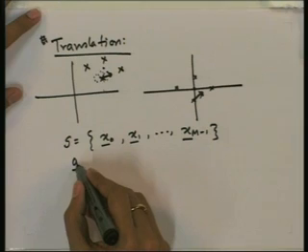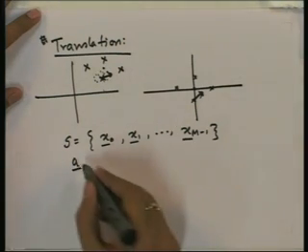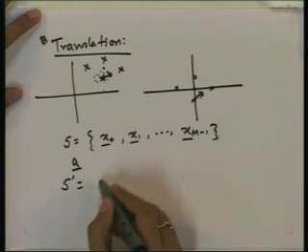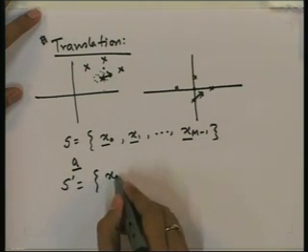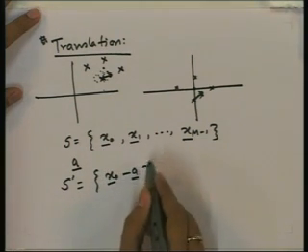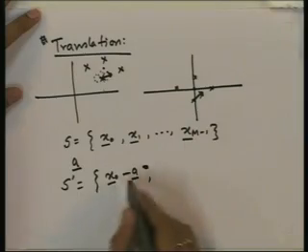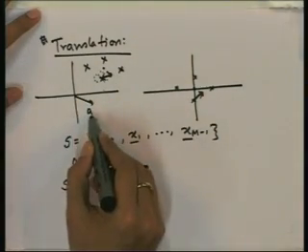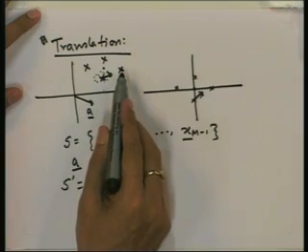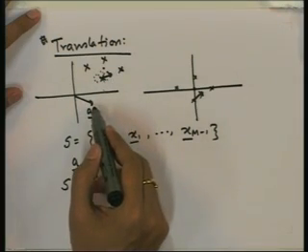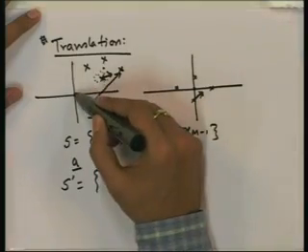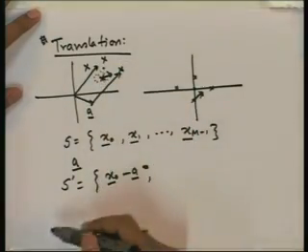Meaning, we have taken an orthonormal basis of the span of the signal space, and with respect to that orthonormal basis we have expressed each signal as a vector of n dimensions. So, these are those vectors. Then we take another vector in the same signal space, and suppose we construct a signal set. We take x naught minus a. Now, what is this? Suppose x naught is this and a is this. What is x naught minus a? It is this.